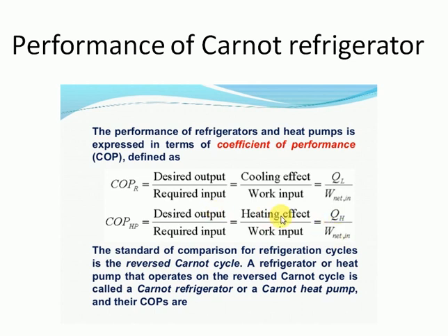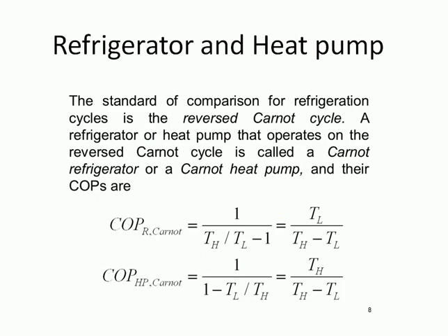So like this, the performance of the Carnot refrigerator can be compared by using the term coefficient of performance. Sometimes we cannot measure the net cooling effect, the heat and the work. In that case, we know only the temperatures. If we know the temperature of the atmosphere and the temperature of the room, then from the temperatures only we can calculate the coefficient of performance of Carnot's refrigerator.